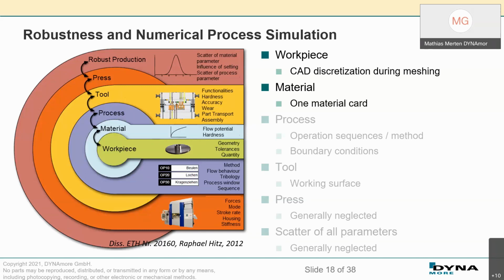The opposite is true, for example, for structural steels, where you just have the minimum yield strength. All the other parameters can be somewhere. You just have specified a yield strength. So describing such a process for a structural steel with a material card where you just know the yield strength you can buy from your supplier, this is maybe a bit tough to do simulation with.